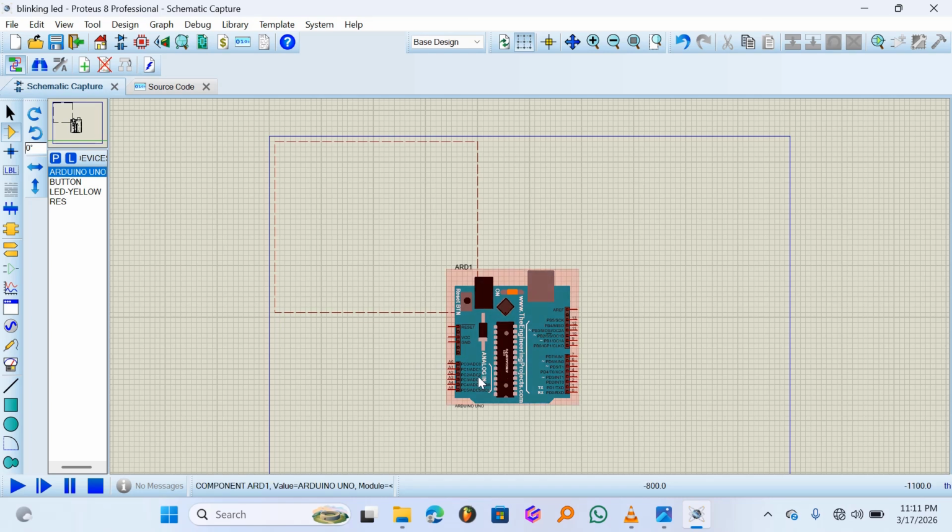You know the analog value changes with point of time. For example, when you connect a sensor here which detects the moisture content in soil, you can connect it here. The inputs are connected from A0 up to A5. Here is where we can connect an input.